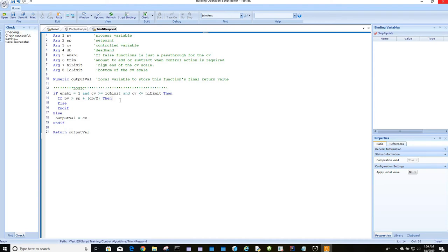design flow. Now you'll notice that you'll have rogue zones that will have a harder time getting satisfied and making it to 85%, where every other zone in the building will. Well, you can adjust that. That's why you have 85. Ideally you want every zone at 100, but that's pretty much impossible. So 85 is just where you start, and you may be able to get more out of your system. You may be able to get all your VAVs with no problem at 92%, and that's great. But if you can't, don't be afraid to go down with that set point.